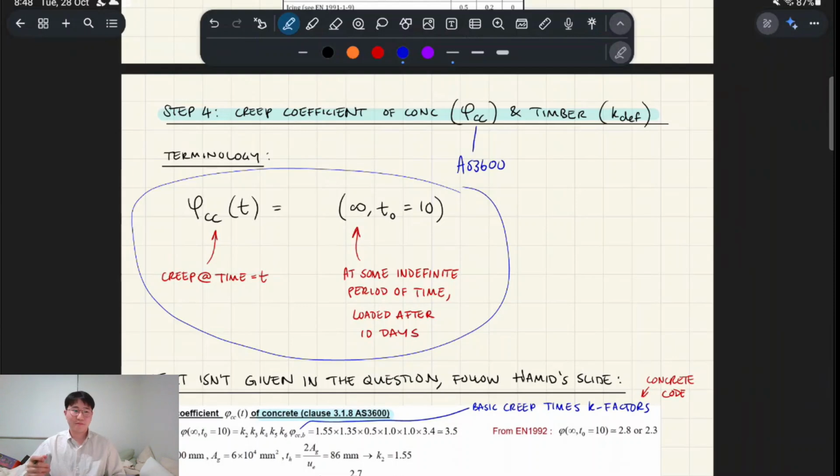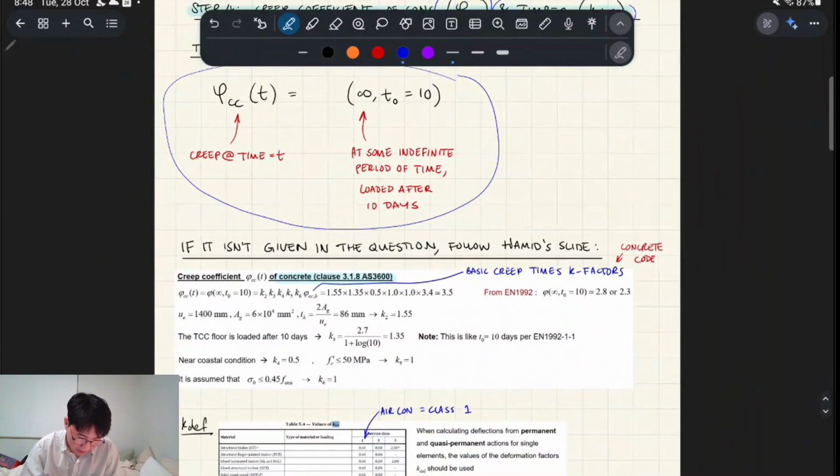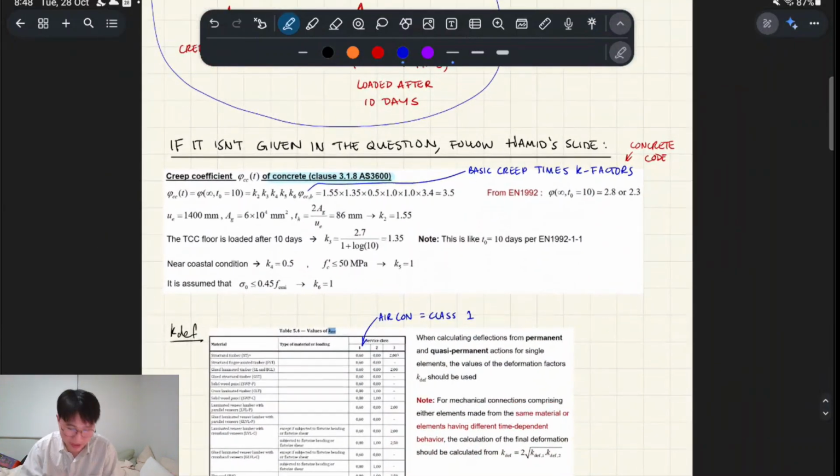A material will deform so much in the long term, but creep is even longer term, over a period of 10 to 30 years. It will keep deflecting. The creep of certain materials will cause your structure to keep deforming, right? That applies to concrete, and that's this creep coefficient, and it also applies to timber, but it doesn't apply to steel, basically.